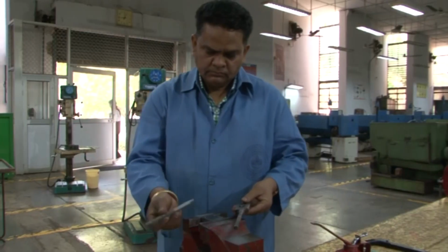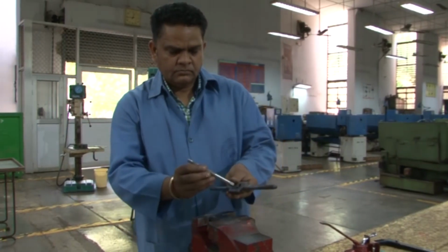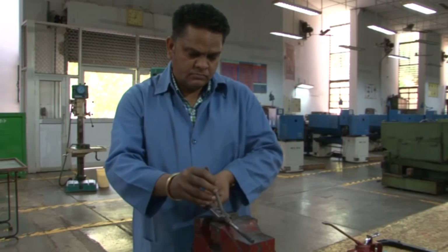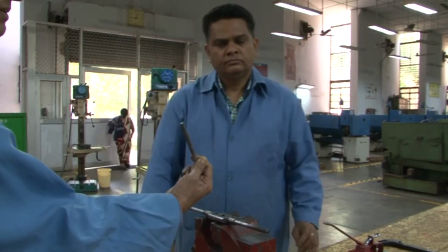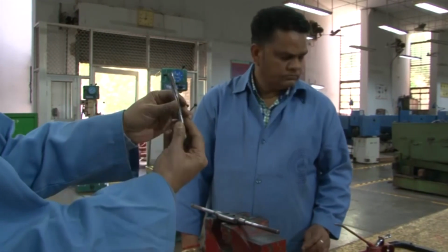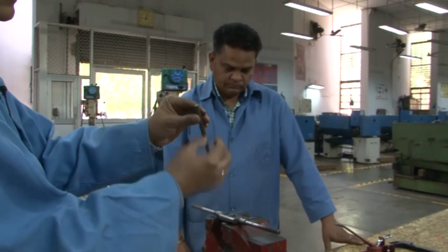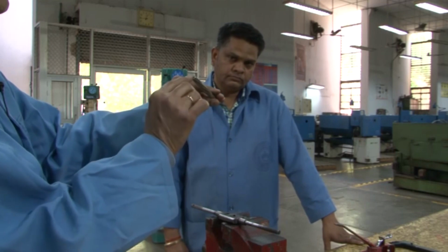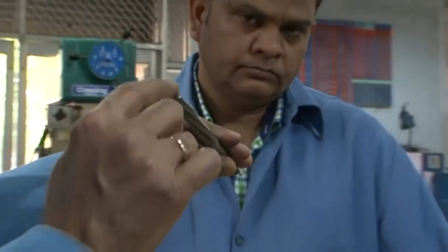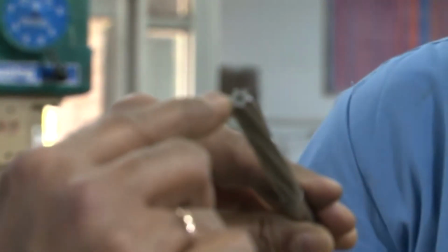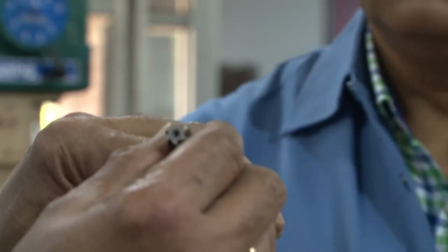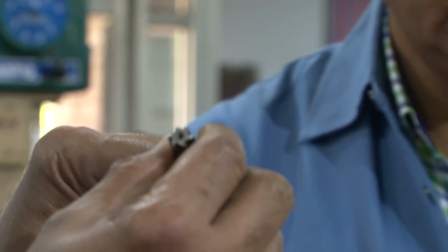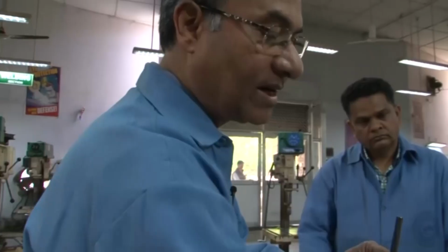Well, now the hole has to be reamed, because the hole accuracy is not very high. For that purpose, this is the reamer, and if you remember, I told you that the reamer teeth are like that. This reamer particularly has 1, 2, 3, 4, 5, 6 teeth. Normally, all reamers will always have an even number of teeth. There are two purposes for that.